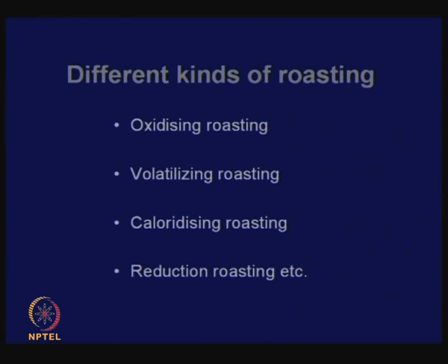Now, in pyrometallurgy, there are three terms which are used very frequently, and you should know what they mean. These are unit processes. Previously, we talked about unit operations, where the physical and chemical nature of the mineral is not changed. By unit process, we mean an operation where we change the physical and chemical nature.